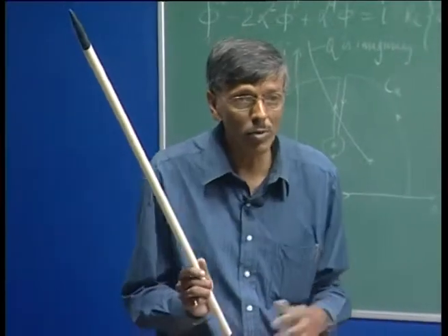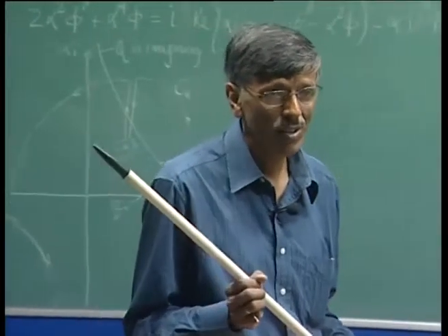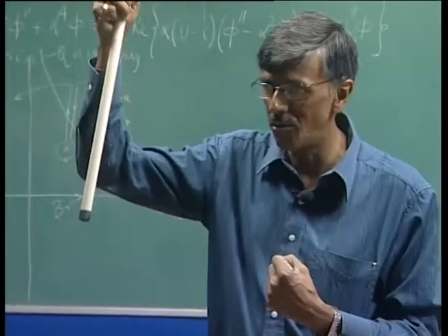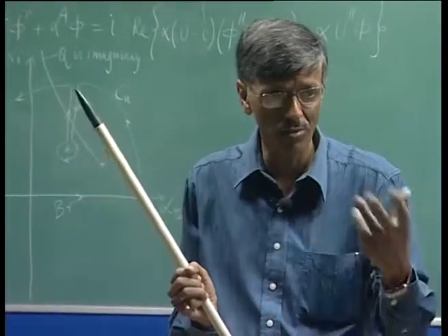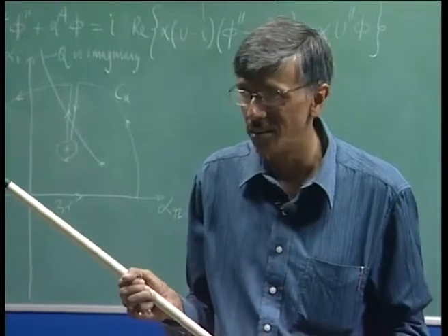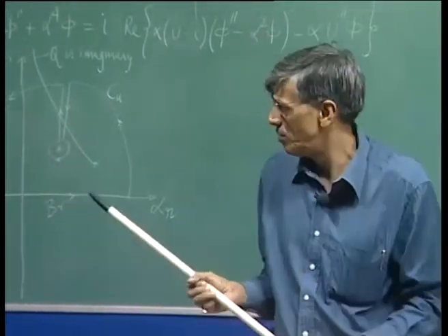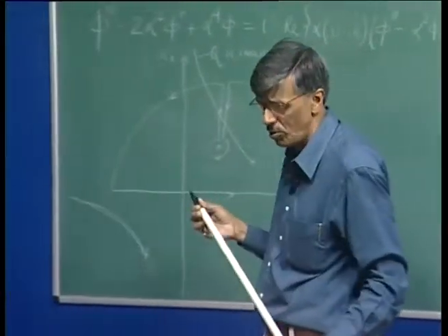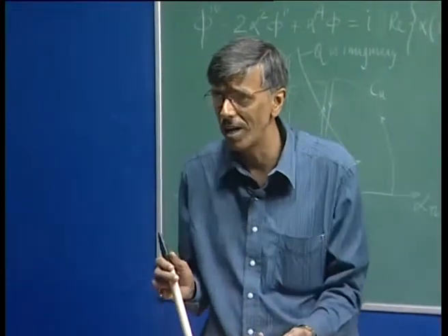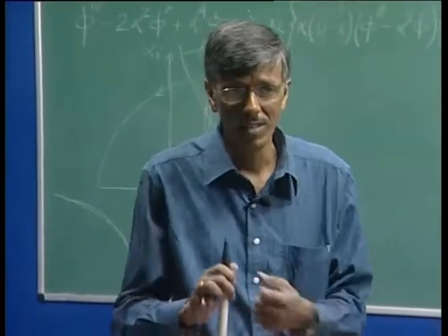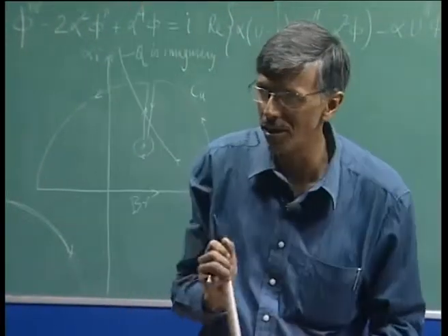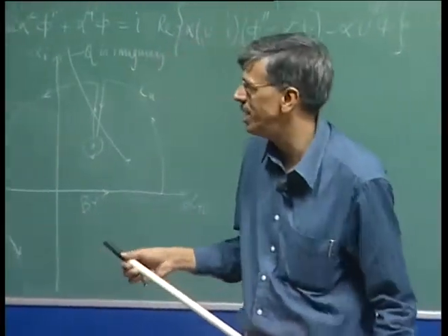What did we do with the boundary layer itself? We actually stretched the wall normal coordinate. That is why we got those similarity coordinates. If you recall from your first fluid mechanics course, when we were told about the boundary layer, how do you get the boundary layer? You stretch the wall normal coordinate. So, same thing we need to do.